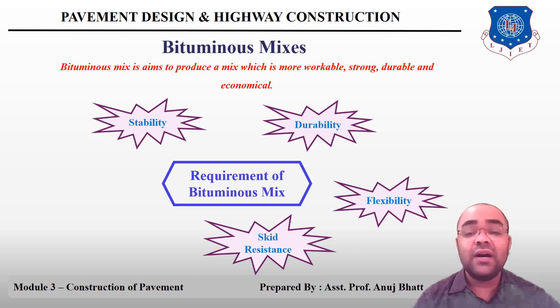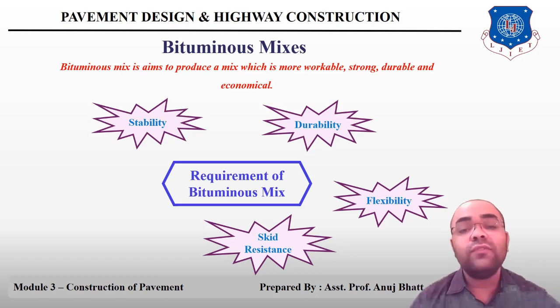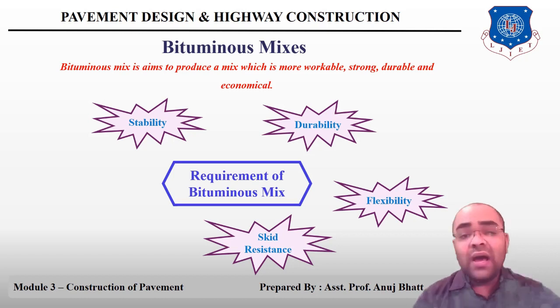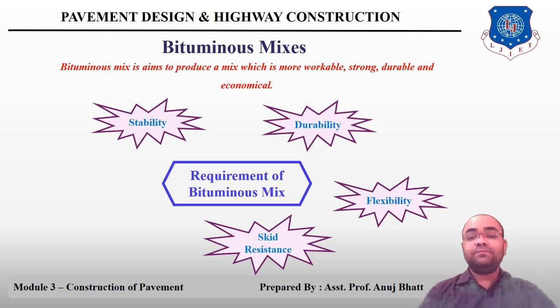Again here you can see that bitumen content is there, so it is very important how much bitumen content you are using in a particular mix. Skid resistance is an important factor in high speed traffic. Normally an open graded coarse surface texture is desirable for skid resistance.